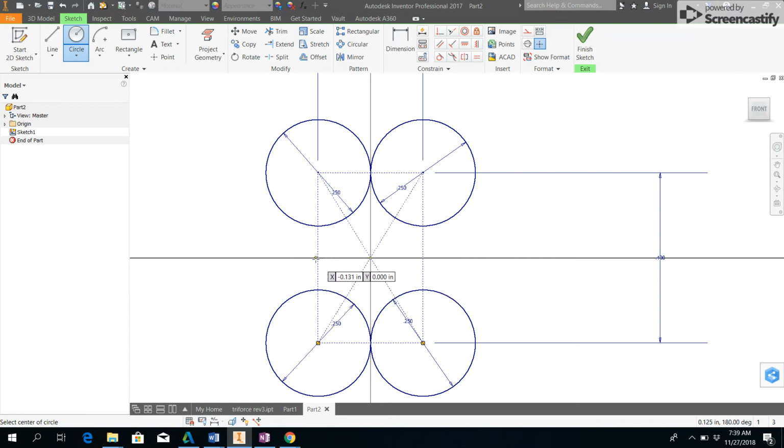And then I can also anchor one right here on the center point of this rectangle. And that was 0.15, but I actually drag it until I get this. If you look real close, there's a circle with a line next to it icon that tells me that these two circles are touching, that they're what's called tangent to each other. And so that way I know that they're locked in there. And that's what I want. So now there's our shape. You should be able to see that holly leaf there in the middle.